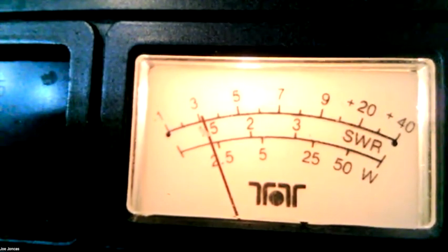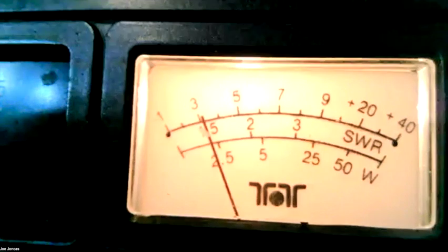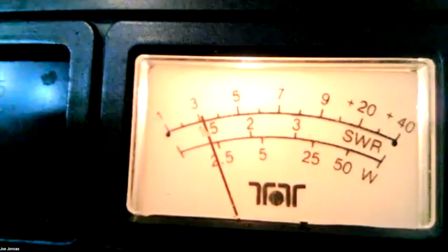But the radios are not as consistent as they should be, but if you've got a decent radio, it's going to give you a fairly good idea of what it is. So if you go to +10, that means it's 10 dB over S9, which means it's a gain where you go from 50 microvolts to 500 microvolts at +10. Now that's a pretty strong signal.